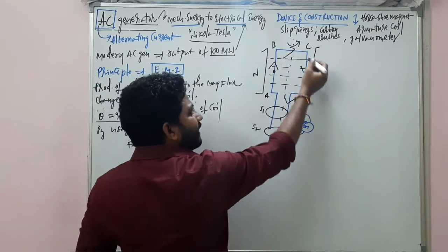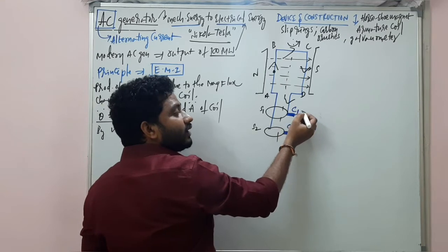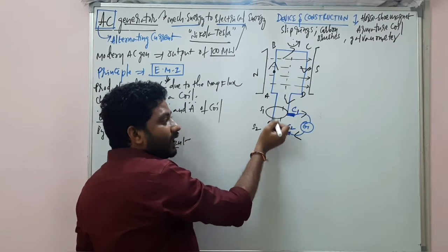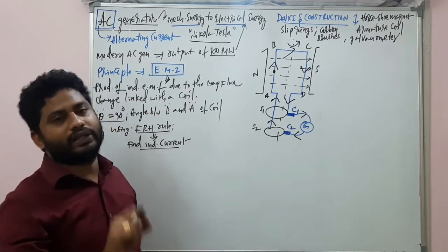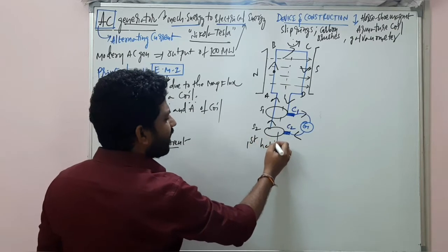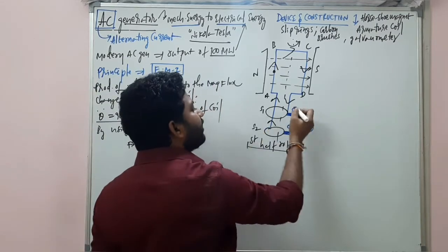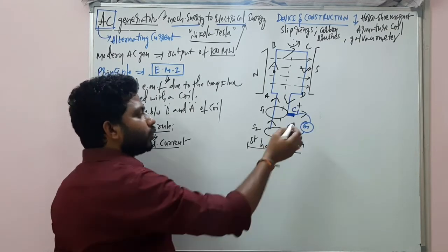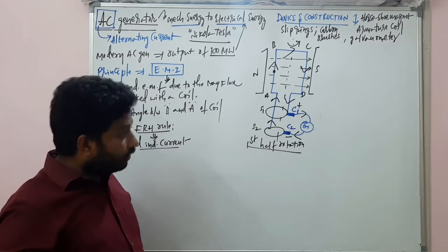Okay. So now current is passing through the shorter lead having connection with slip ring 1. Slip ring 1 is having connection with C1, and from C1 the current passes in this direction through the galvanometer to C2. C2 is having connection with slip ring S2. Understand? Clear? In this way, current flows through the coil in the first half rotation. So in the first half rotation, what happens here that you should understand: carbon brush 1 behaves as a positive terminal, carbon brush 2 behaves as a negative terminal. Yes or no, my dear students? Carbon brush 1 behaves as a positive terminal. That means current is flowing in this direction. Okay? Clear?